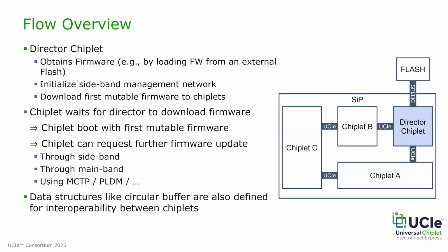And we have provision for existing protocols like MCTP, which is the Management Component Transport Protocol, and PLDM, Platform Level Data Model. So you can use that and do further upgrades for firmware downloads. To ensure seamless interoperability between chiplets, we have defined data structures like circular buffers that allow for efficient communication and coordination for these firmware downloads within the SIP, right? So that's one thing that we have done.